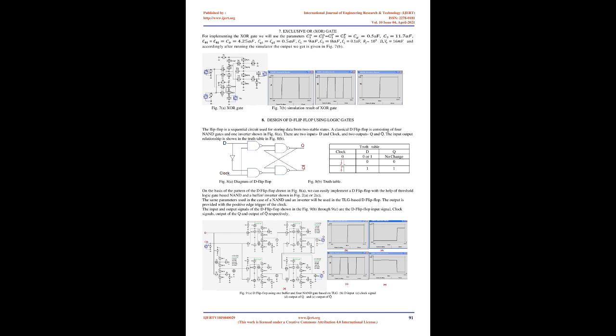3. Multiple input threshold logic gate. The multiple input threshold logic gate consists of a tunnel junction and n multiple inputs connected at points A and B. Each input voltage for the upper side is connected to point B through a capacitor, and each input voltage for the lower side is connected to point A through a capacitor. A bias voltage is also connected to point B through a capacitor. Point A is grounded through a capacitor C_0. The capacitor of the tunnel junction is C_J.